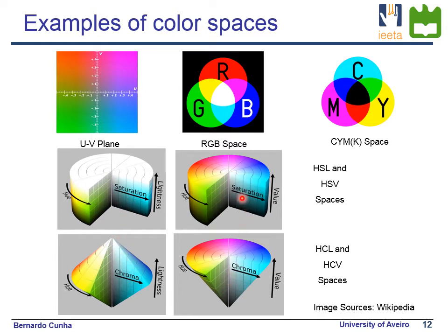And HSV stands for hue, saturation, and value. Hue is represented as an angle along the outside of this cylinder, so a circumference, and hue represents chrominance, color. So basically it will start around the red and then go around all these colors and go back to the starting point. So you can define hue as an angle typically between 0 and 360 degrees.